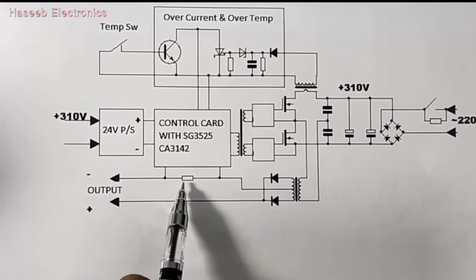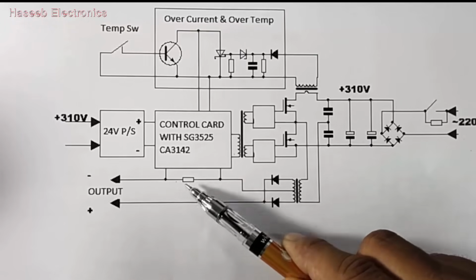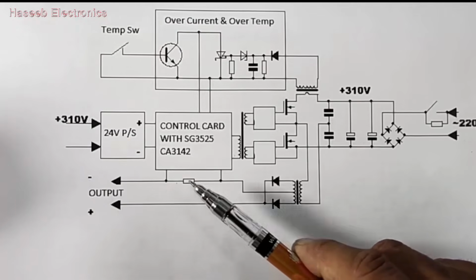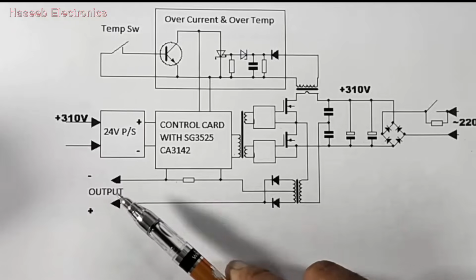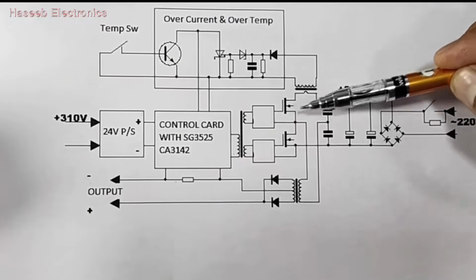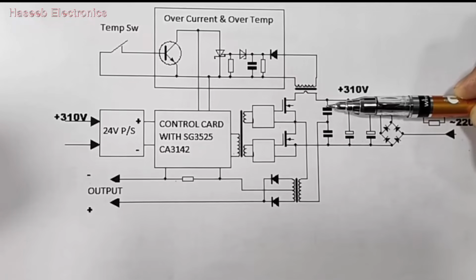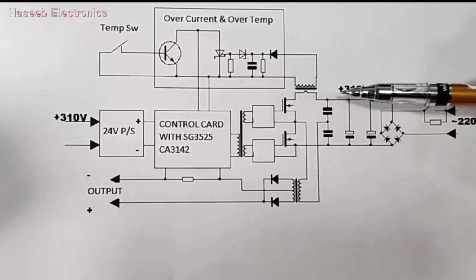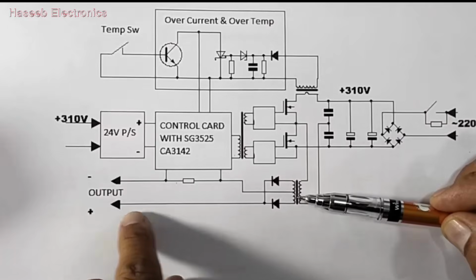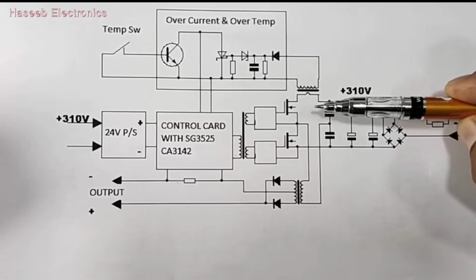As I said, this is a current based power supply. To control the current we have a shunt resistance here. This shunt resistance is used to measure the output current, and here we have input current measurement. Why do we need this? Because for switching we use 5 or 6 or more MOSFETs in parallel to switch a high amount of current. If we need 200 ampere in the output, we need a high amount of current.